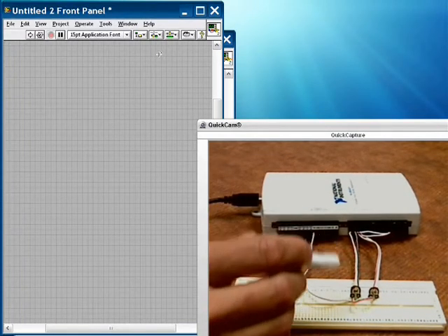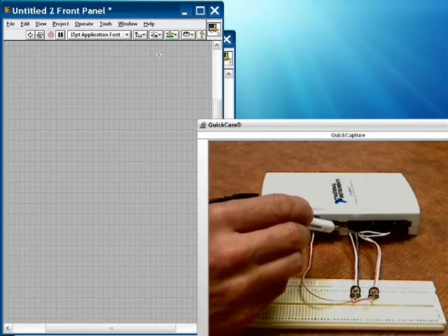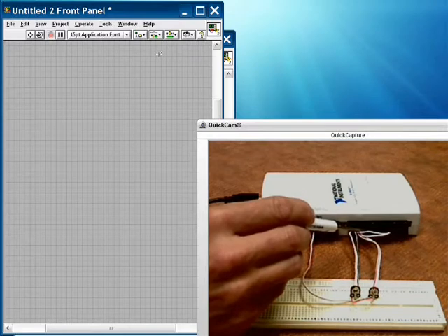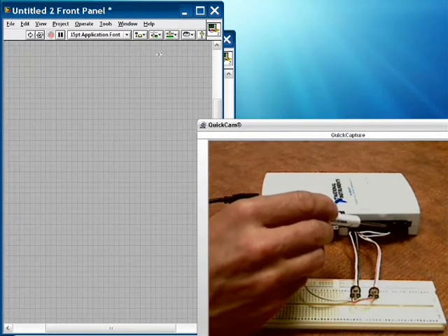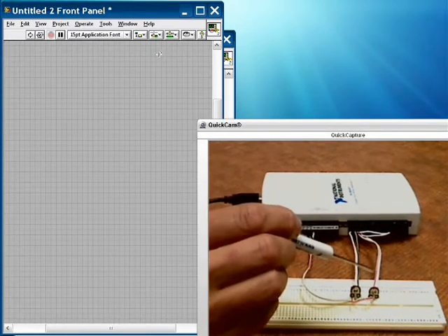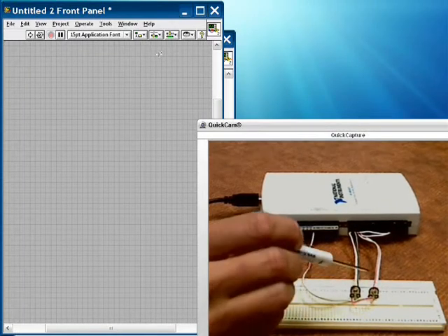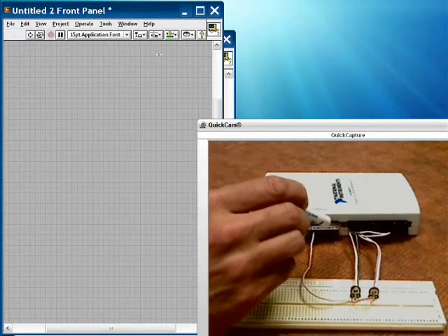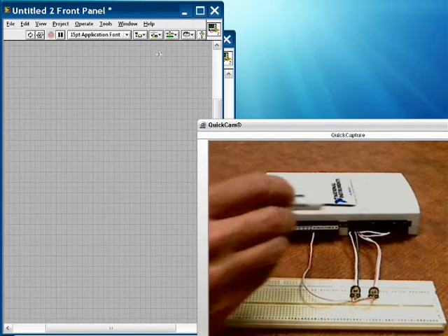Coming out of the potentiometers, we have the low side signals going back to the ground side, or the low differential side, of our analog input channels, and then we have those wired over here to the system ground of the USB 6211. In the center of the potentiometer, with a voltage that's going to vary with the motion on the potentiometers, we have a signal feeding right into our analog input channels 1 and 2. So this is our setup.